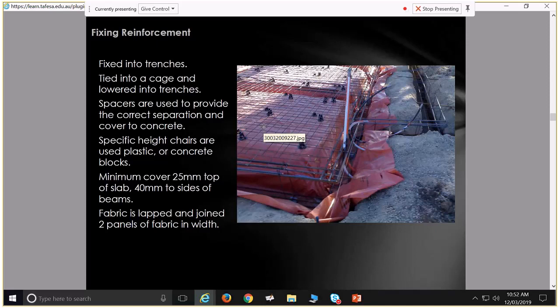I don't do slabs, but you were saying they use quarry rubble and quarry sand. Normally they use that orange sand nowadays and they just run it loose and whack it afterwards. Yeah, it all depends on the quarry you're getting it from, what the supply is and what the dissolved salts are in that location. So you have to be careful about that. Well, if you're using plastic underneath, don't be so careful about that, I was just going to say, stop it coming through.